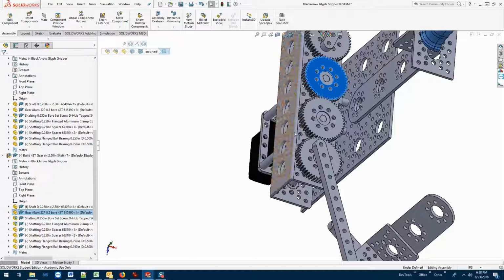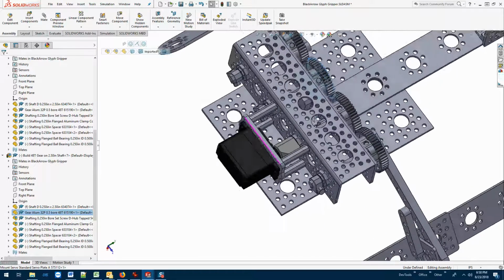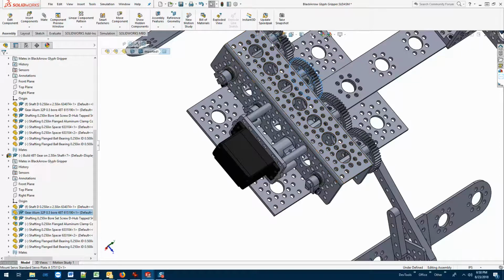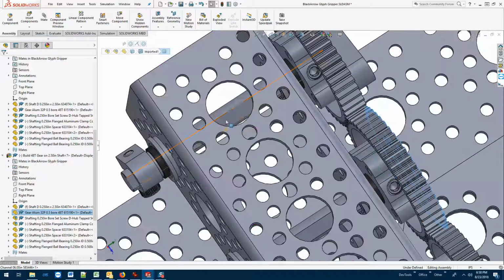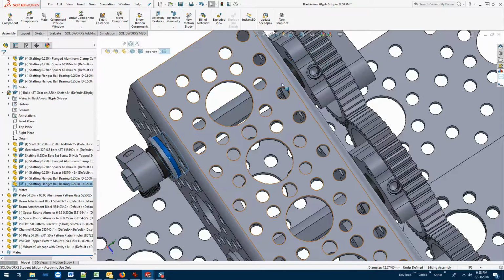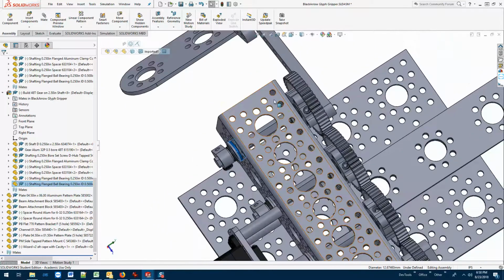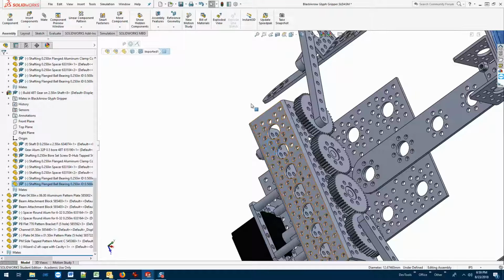The channel is just going to give us these big holes, because the gears are physically attached to shafts that run through bearings mounted to the big holes. In SolidWorks, I'm just going to take the shortcut of mating the gears to some big holes so that we can see the basics of the gear mate.